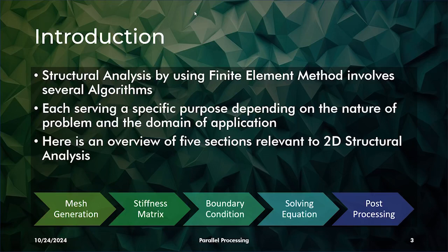When we have our stiffness matrix, we can apply our boundary conditions, and some of the rows or columns of our matrix are going to be changed. We have many boundary conditions. It can be load, it can be pressure, it can be other constraints. Next, we're going to solve the equation. We have a matrix that we're going to solve and measure the U. After we solve the equation with a specific solver, we use the results to measure some other variables or quantities like stress.